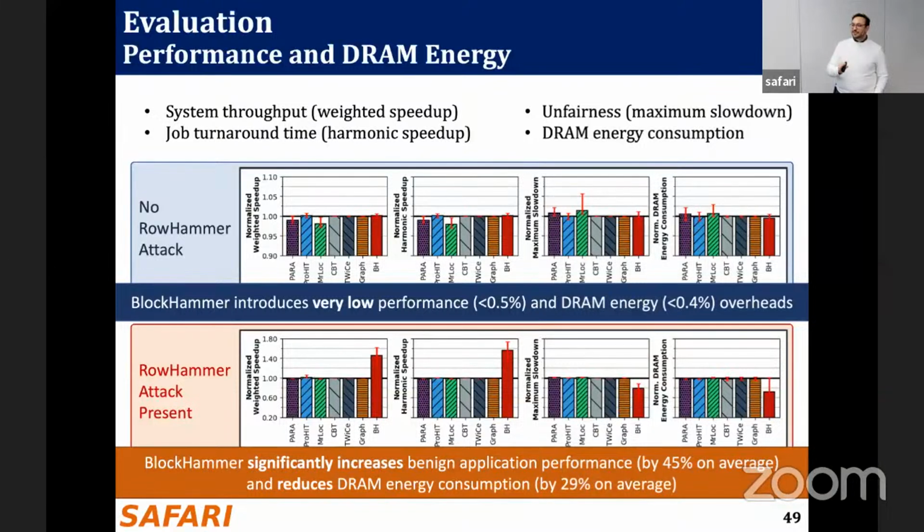In the baseline, nobody actually interferes with the RowHammer attack, and the RowHammer attack is consuming a lot of memory bandwidth. When we introduce BlockHammer, it alleviates that problem and helps benign applications finish faster. Okay, you increase the fairness. Fairness among benign applications, yes. I see. Because a RowHammer attack is a malicious threat, right? So we do not want a malicious threat to consume our resources.